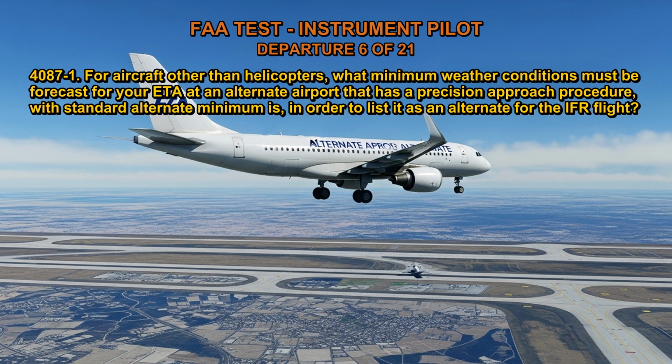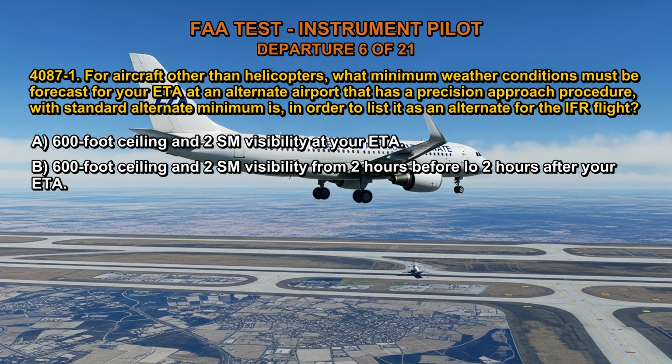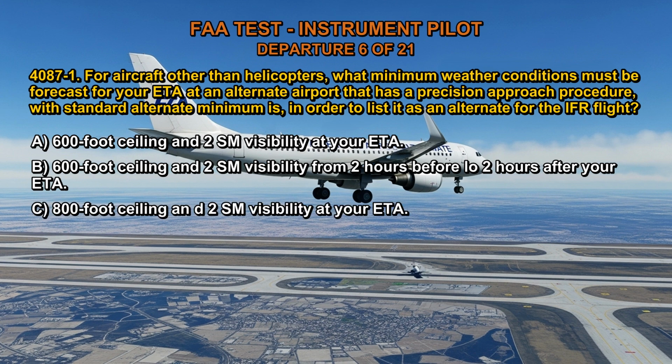4087-1. For aircraft other than helicopters, what minimum weather conditions must be forecast for your ETA at an alternate airport that has a precision approach procedure with standard alternate minimums, in order to list it as an alternate for the IFR flight? A. 600-foot ceiling and 2 SM visibility at your ETA. B. 600-foot ceiling and 2 SM visibility from 2 hours before to 2 hours after your ETA. C. 800-foot ceiling and 2 SM visibility at your ETA. The correct answer is A.